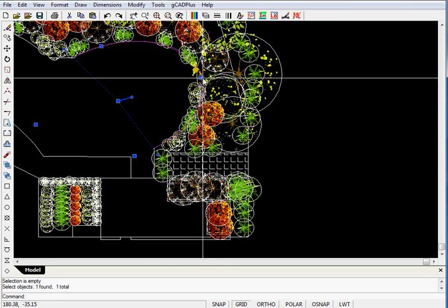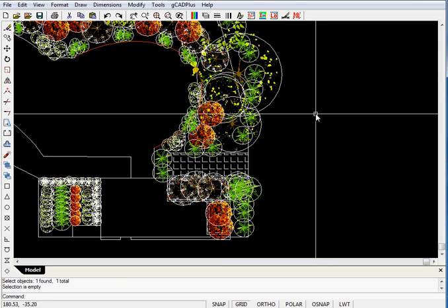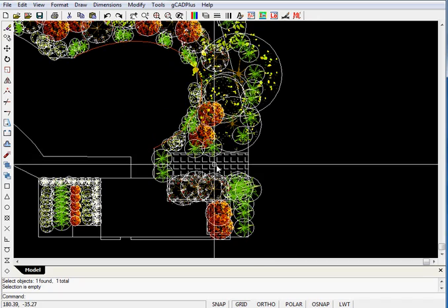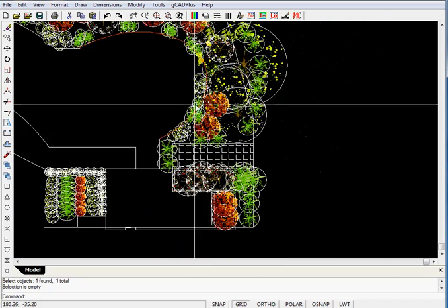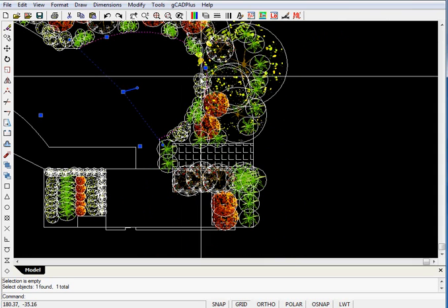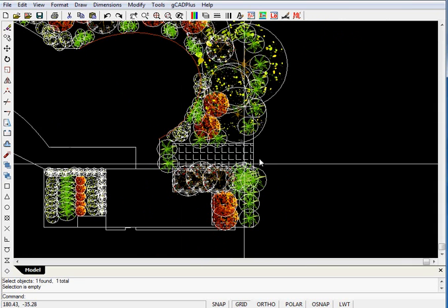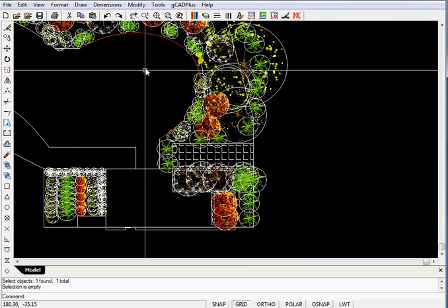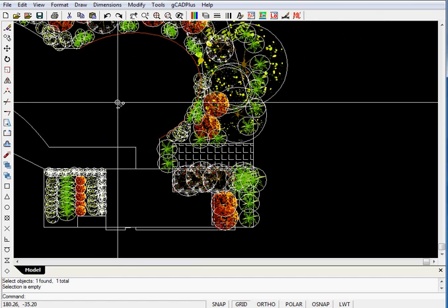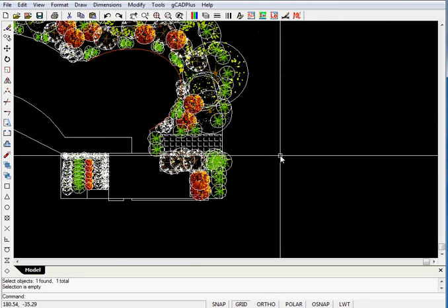That's because you've got Bezier curves here now, and it gives you quite a nice flowing and informal curve, and you might in this design need to move some of your plants around. So if we come back here and bring it in to that point there, we are much closer to the original designer's aim for that ellipse running through there. So I hope that tells you a little about the use of the ellipse command.